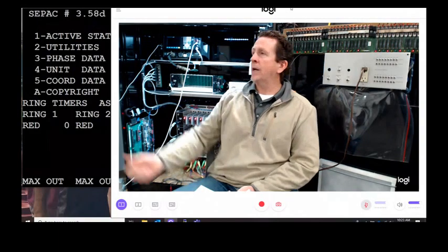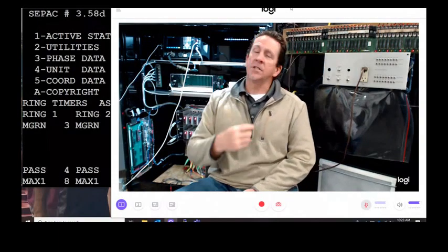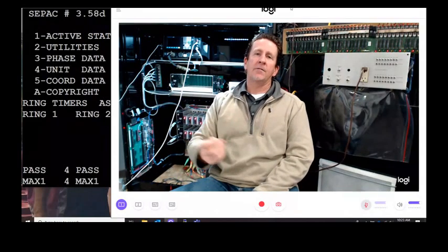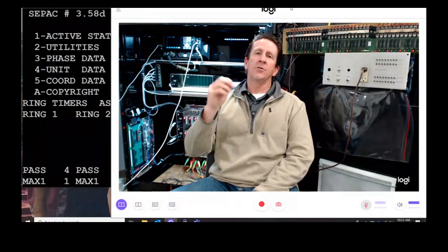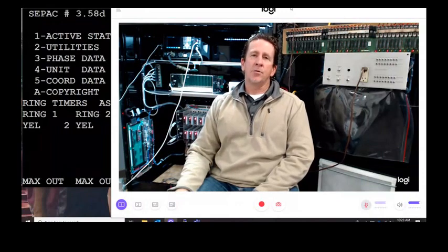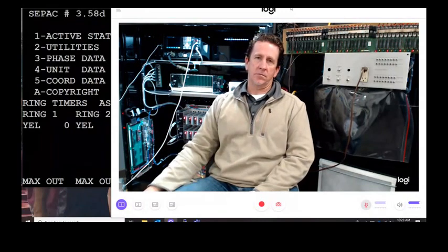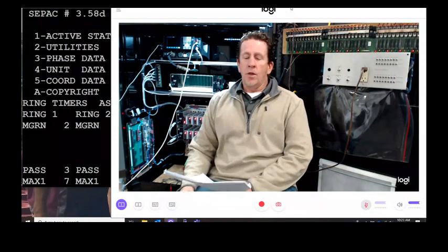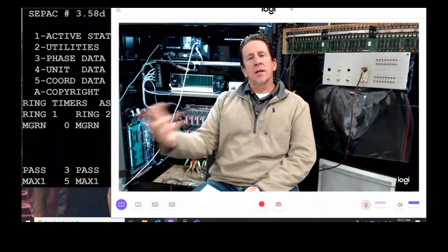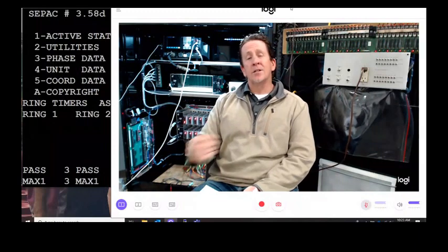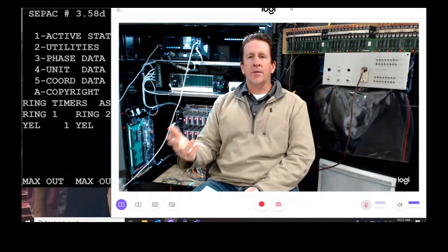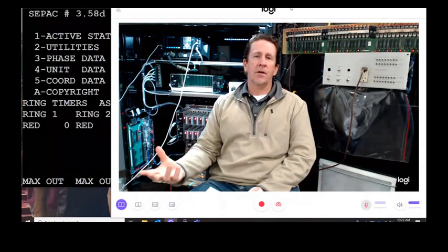As we're operating, I'll demonstrate it over here, you'll see a bunch of transmit and receive lights sending the data back and forth, from BIUs to controllers to MMUs over the SDLC assembly. When we ask whether it's transmitting and receiving, we're basically talking about the LEDs flashing on and off. It's an easy identifier. If that's not happening, then we know something went down in the bus and it's not working.